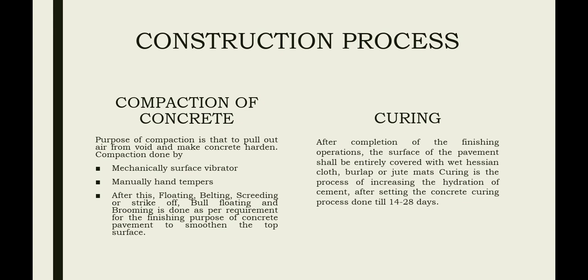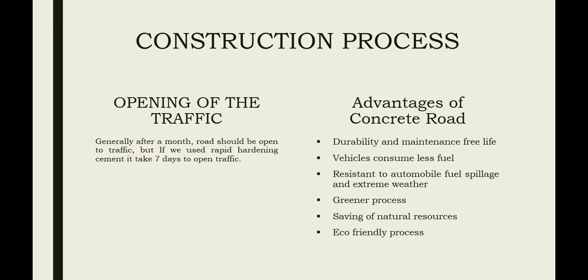So after completion of the finishing operations, we have the curing. The surface of the pavement shall be entirely covered with wet Hessian cloth, burlap, or jute mats. Curing is the process of increasing the hydration of cement after setting the concrete. The curing process is done for 14 to 28 days. Opening for the traffic. Generally, after a month, the road should be open to traffic, but if you use rapid hardening cement, it takes 7 days to open to traffic.